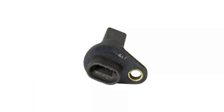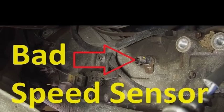What does P0720 mean? P0720 is a diagnostic trouble code (DTC) that indicates a problem with the vehicle speed sensor (VSS) circuit. The VSS is a sensor that monitors the speed of the vehicle and sends this information to the powertrain control module (PCM). The PCM uses this information to control various functions, such as the transmission, speedometer, and cruise control. P0720 on some Ford vehicles.